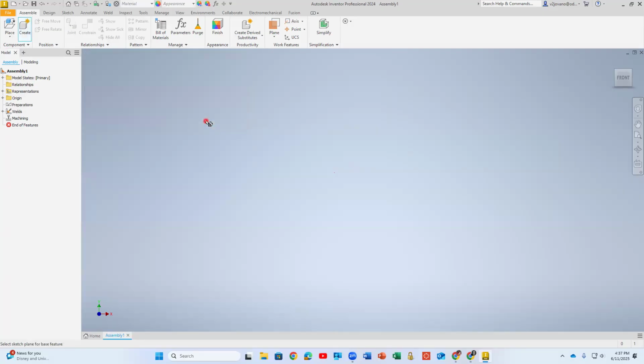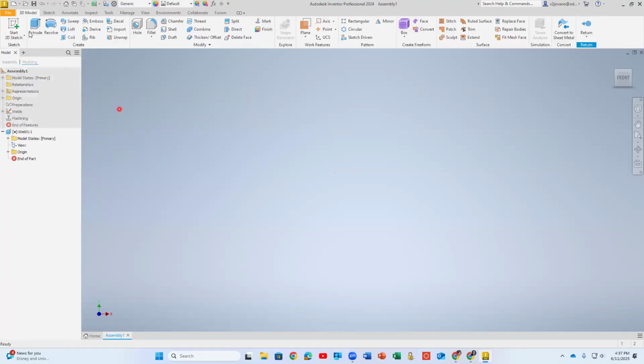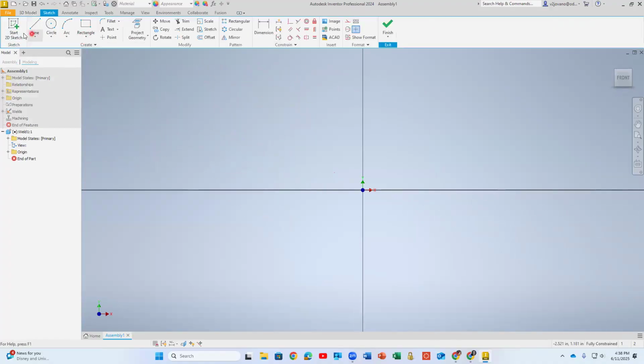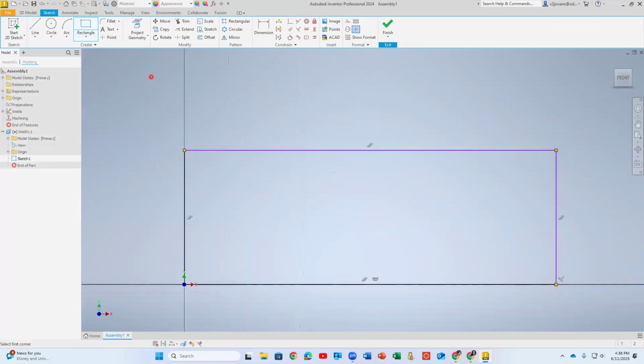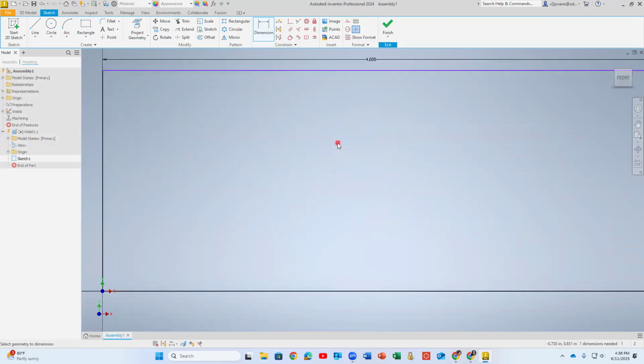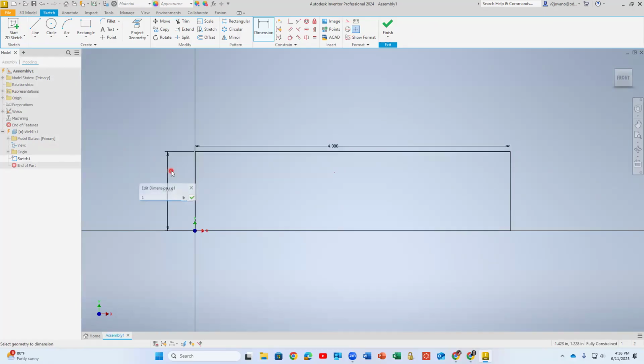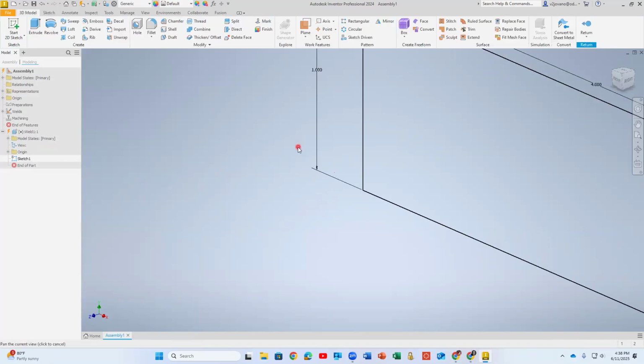And then inside of that part, I'm clicking anywhere, or you can make that same part outside of this and then insert that as a drawing. So you see, I'm making just one simple rectangular shape. The dimension of that rectangular shape will be 4 inches by 1 inch. Middle mouse click twice every time you change dimensions, so it can perfectly fit and you can see everything on your screen. And then 1, and that's it. Finish.